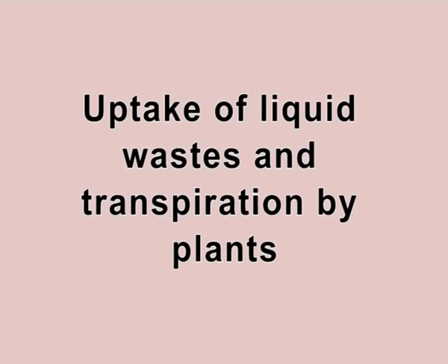Adsorption of organics in the soil particles and uptake of nitrogen and phosphorus by plants and soil microorganisms is another additional benefit. Another one is the uptake of liquid wastes and transpiration by plants. Percolation of water to groundwater also contributes in the irrigation process.